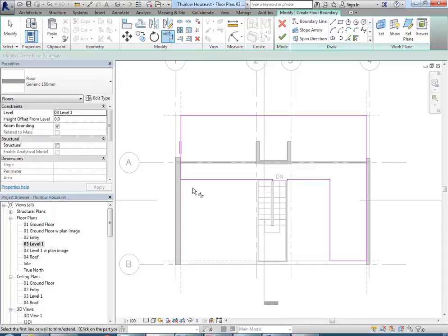Yeah. So escape, and then switch to your level 1 floor plan. No, your other one above that. Yeah. And then you can see any lines that are missing or lines you need to join together. So you need to see how mine's got a closed shape going all the way around. So you need to draw a line across the top and then connect your lines at the side to the line at the top, and also connect any other lines that you have.